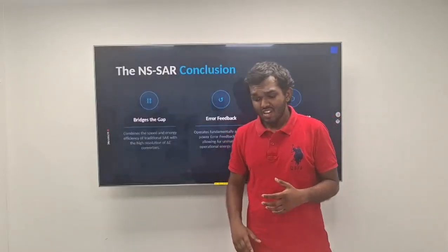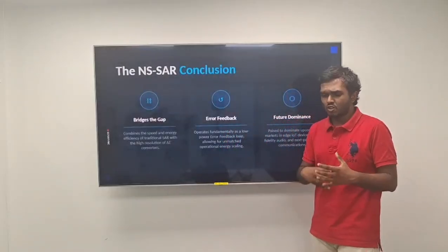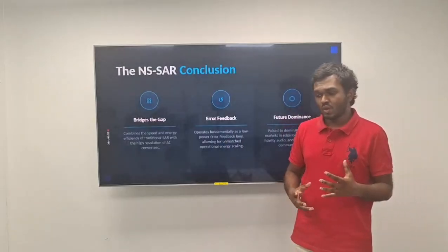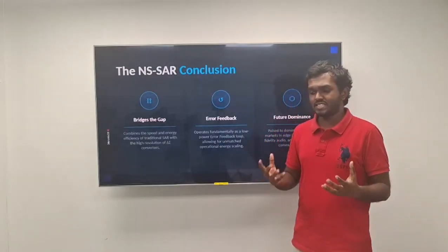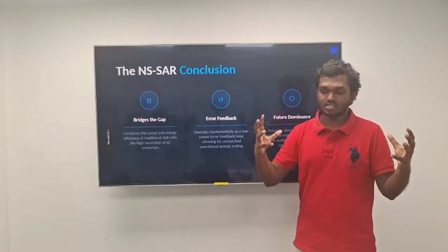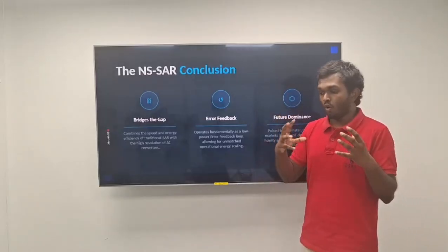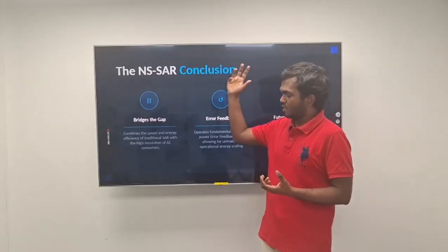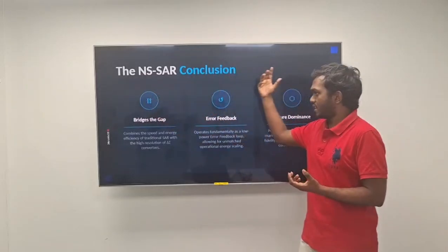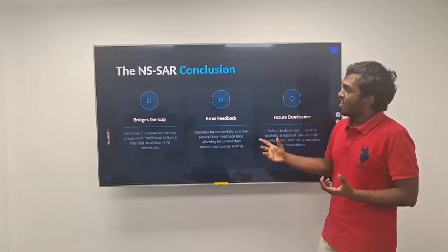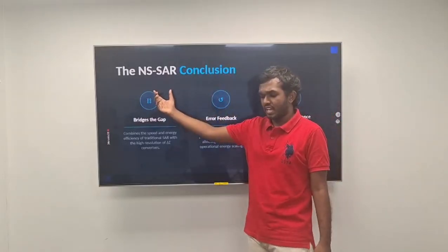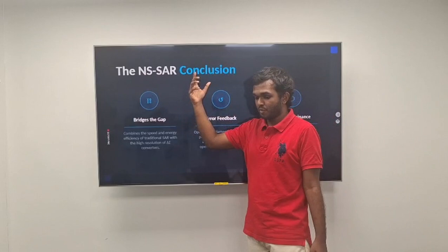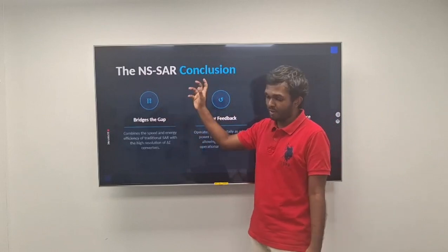And now for the conclusion. Noise shaping SAR basically took the best parts of two older ADCs. First one is SAR ADC, second one is Sigma Delta ADC. The SAR ADC is mainly popular for speed and low power.